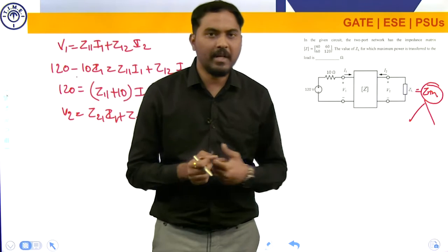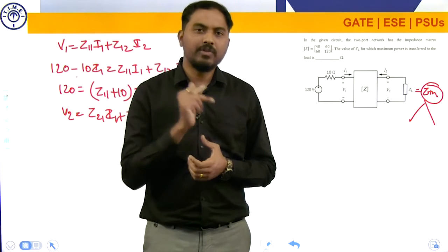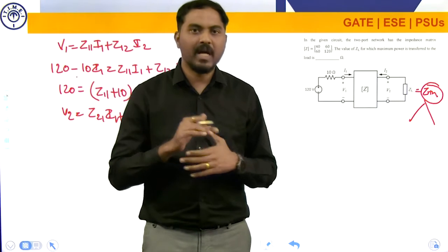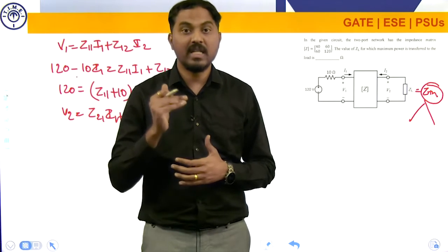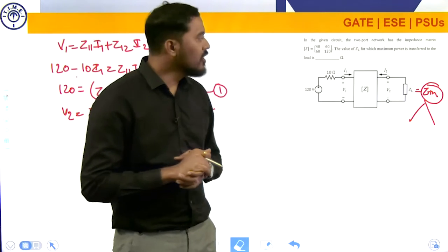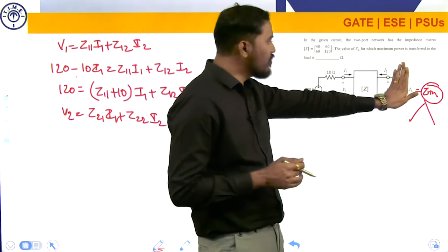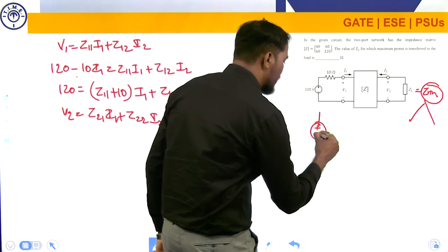Simply you are going to take a multimeter and connect it across those terminals. What exactly do you think that multimeter is doing? It is applying some voltage across it and measuring some current through it. The ratio of voltage across it to current through it is nothing but the resistance offered by it, right? So, the same thing I am going to do here. Step number 1, remove the load. Assume that this load is open. Okay, I will redraw the circuit.